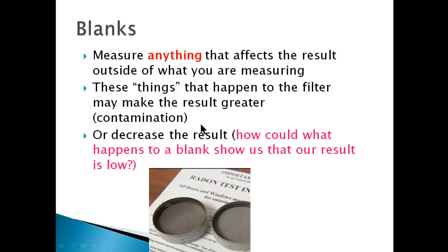Well, what if there was already dust in your plastic bag and it got on both the filter that you put in the Minivol and your blank filter? Well, in that case, the blank shows a result, and that's contamination, and then you know I've got to subtract that off of my Minivol filter because that got on both of them, and that's the purpose of a blank.